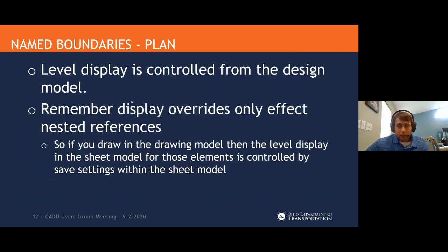Okay, so to reiterate, it's being controlled from the design model. That's what people want to do. You've got like 20 plan sheets. You don't want to have to go into 20 sheets just to turn a level on and off. You want to be able to control that from the design model and have that push through to all those plan views. So I'm going to say it probably 100 times here: nested references, when we're talking about the display override setting on that reference setting.